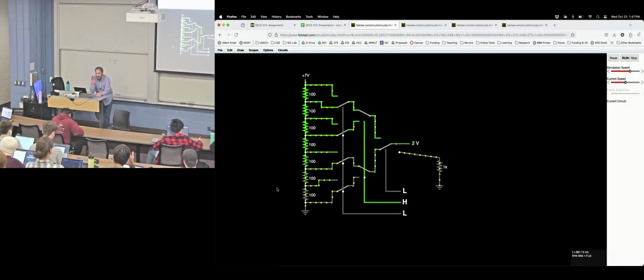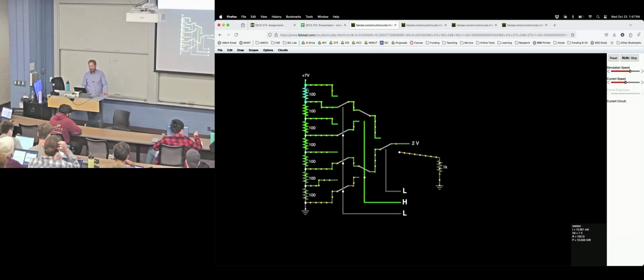One thing that is nice is that all these DACs we're going to see today are actually pretty fast. The voltage is available immediately. It's not like the slope integrator where you had to do something over time. With the pulse width modulation, maybe you can make an argument that it has to take some time because you have the low pass filter there. So this one's done immediately. It just costs a lot in terms of area, resistors being large structures, and you have to have a resistor basically for every voltage that you want to put out. So that's a disadvantage. We'd want to figure out a way to get fewer resistors in our DACs to make them smaller and more cost effective.